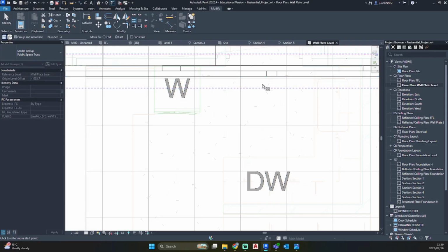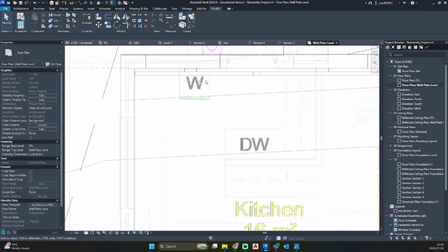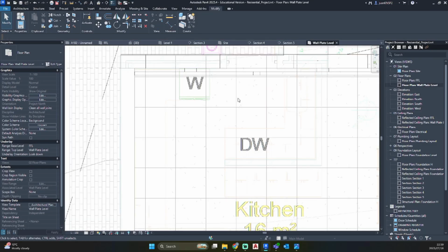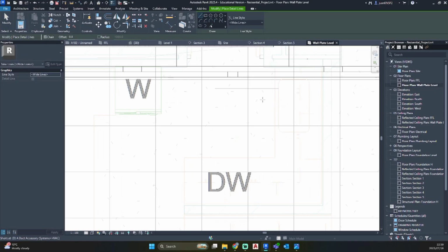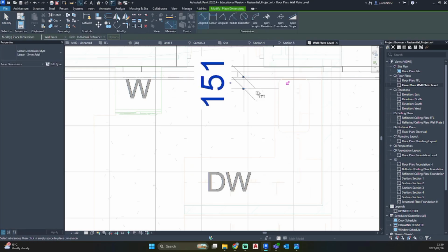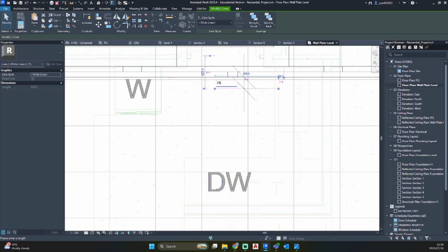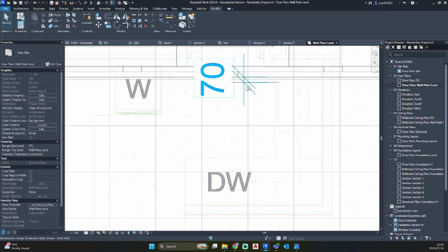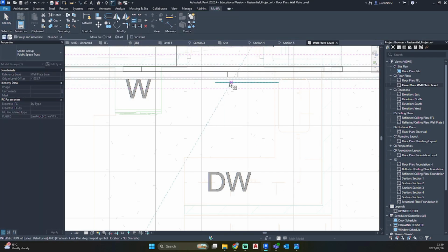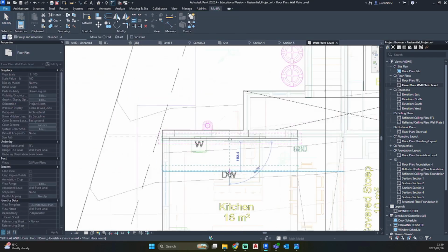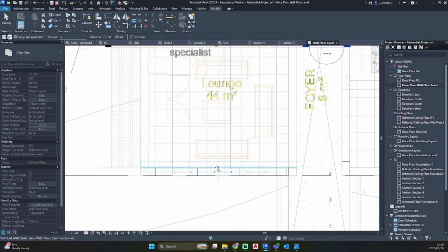Since that one's not showing, no idea why, I'm just going to create a line with an offset of 70, so I know that line is where my other bracket is. So I'm going to click on my roof truss, click on array, click on that area, move it all the way down to the other side of our parapet wall.